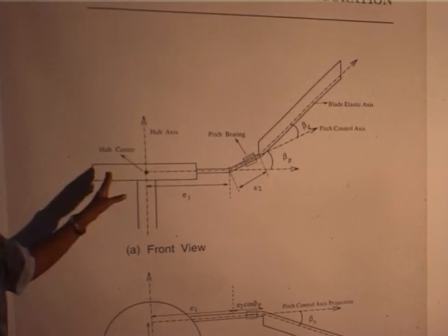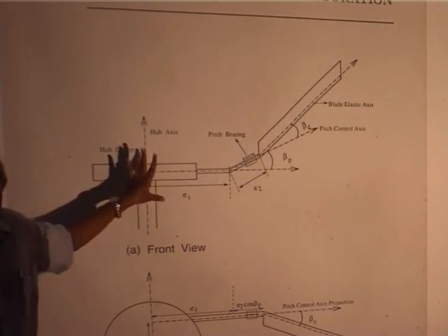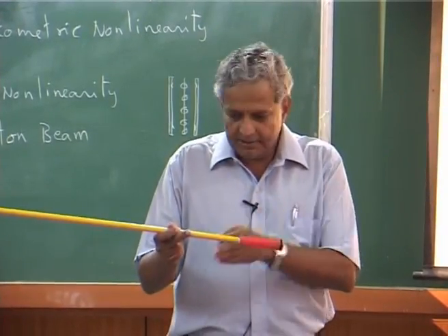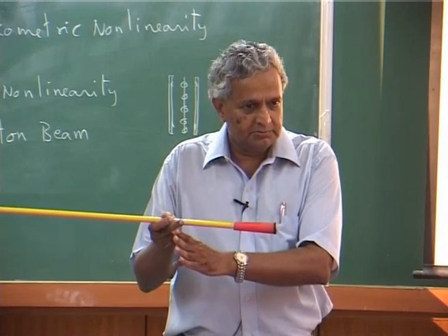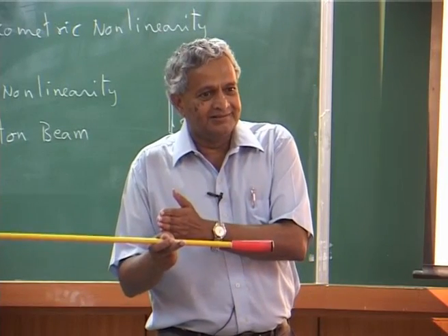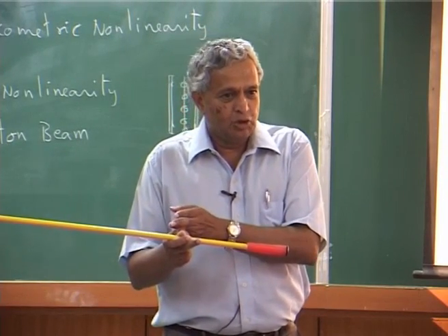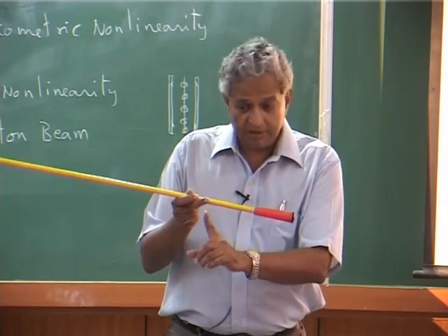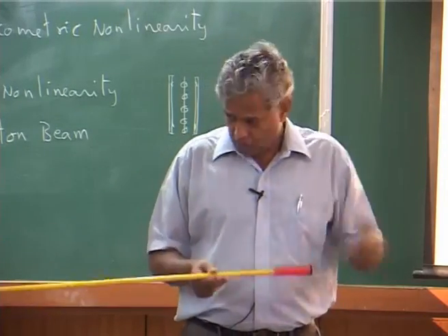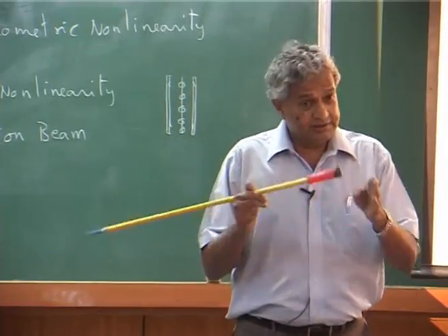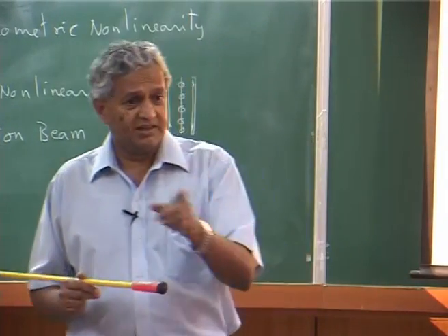Okay, this is a hingeless blade, I can design like this. I am just showing a schematic. If you take an actual blade, you can have the hinge near the hub, and the pitch can be outside, no problem. Or the pitch can be inside and the hinge outside. Say the flap hinge is inside. Then when it flaps, I will show you that geometrical thing, how it happens. That is why this was always a question: where do you put the hinge?